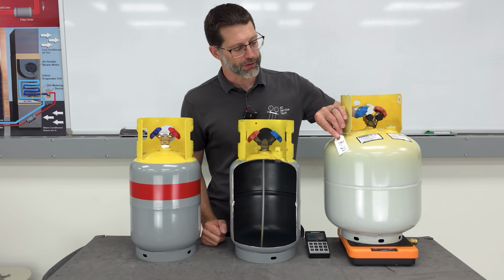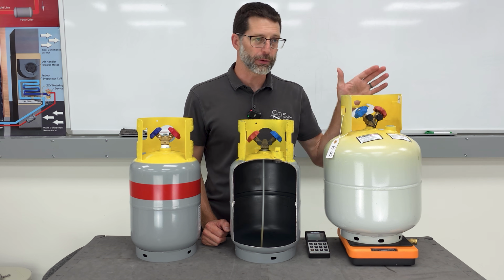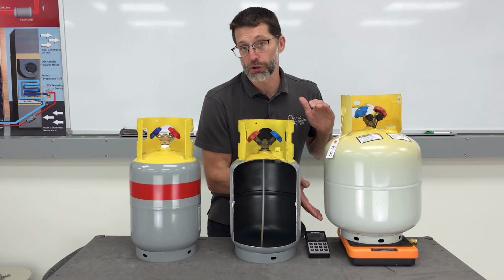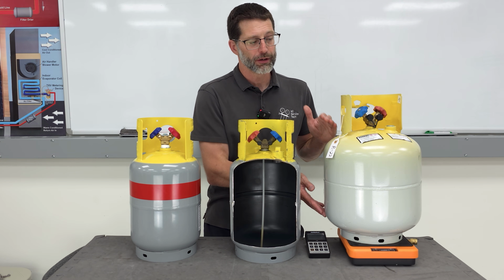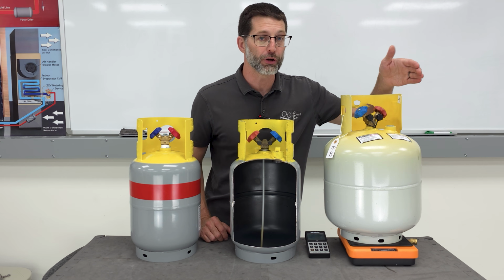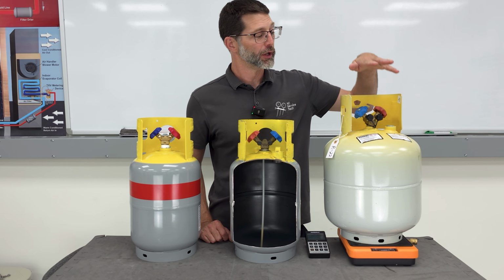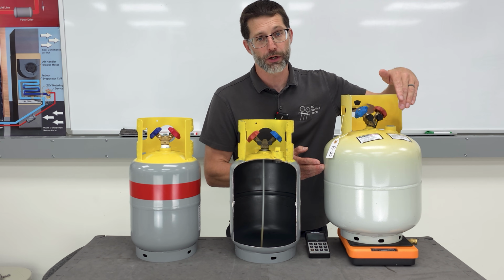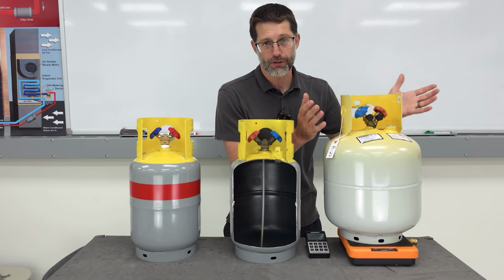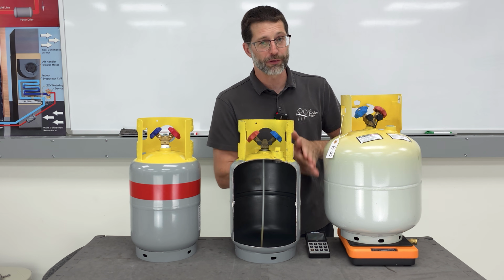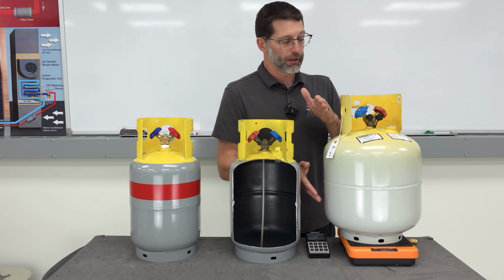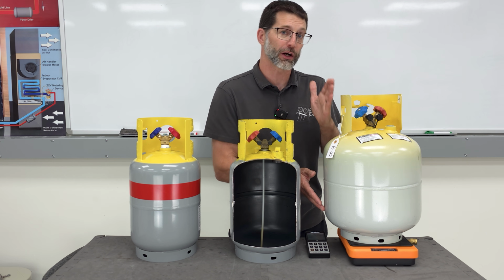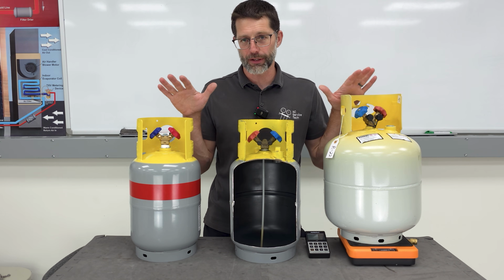Anyway, the other thing is we would exchange these refrigerants at the distributor, and if we had air mixed with the refrigerant, they might think that the refrigerant charge is contaminated. We want to make sure that we don't get any air into the recovery tank. We would need to, say, purge the hoses or vacuum the recovery hose setup before recovering refrigerant into a tank. Anytime you get air in the tank, it's going to always measure a higher pressure compared to saturated temperature. The other thing is that the recovery machine might go off on high limit. It's not going to be able to push the refrigerant in here if you have a lot of air in here, because the pressure in the tank will be too high to overcome by the recovery machine. So just keep those types of things in mind.